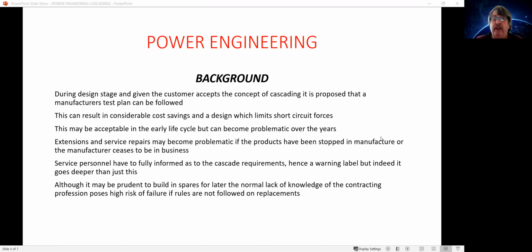in terms of the actual cost of breakers, which is fundamentally linked to the kA rating of the breaker. Breakers with higher kAs generally command higher constructional costs, and therefore they end up being more costly to supply downstream.